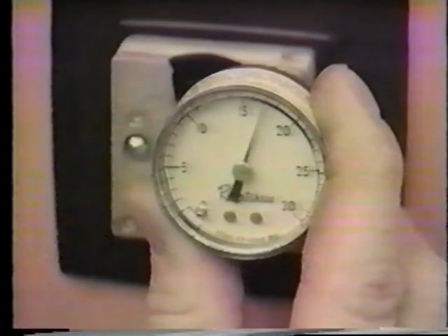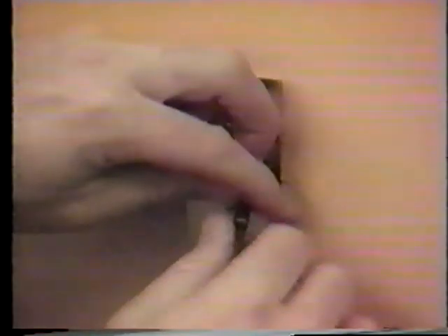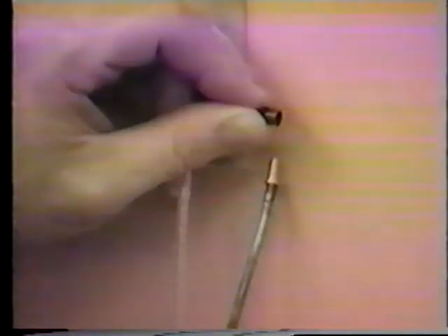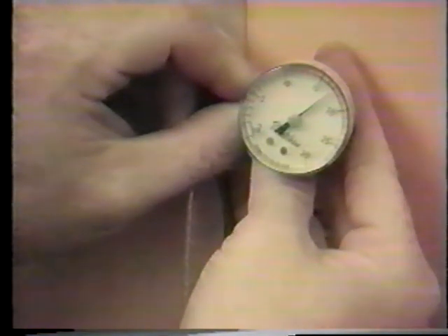If it does not reach at least 15 psig, remove the thermostat from the wall, pull the main air line from the back of the thermostat, and check its pressure. If you do not get a minimum 15 psig reading on the main, then go to the pressure reducing station and check its setting. If its output is set for 20 to 25 psig, look for leaks in the system.